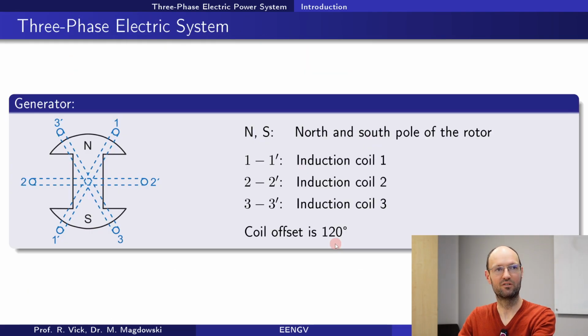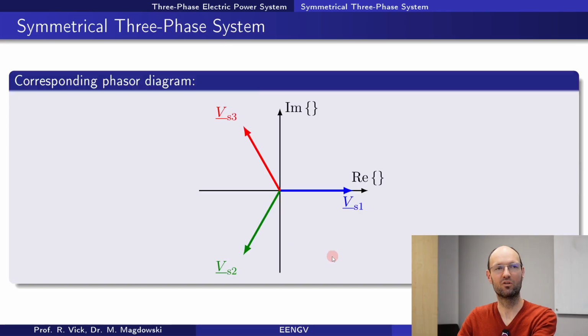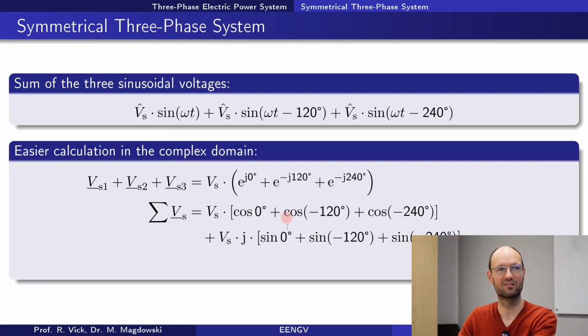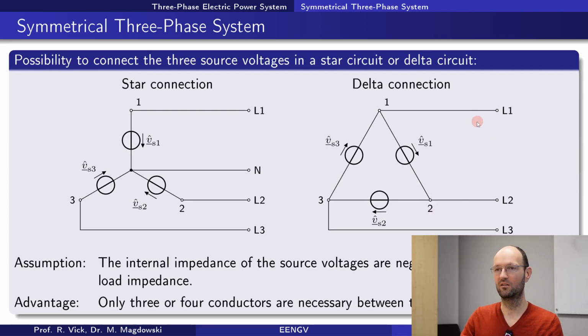And the advantage of this interlinking, this connection of these voltages, in German we say Verkettung. I've not really found a meaningful English translation for this, but all the mathematical properties that we just discussed, that the sum here is 0, this helps us in the end so that we can transmit 3 times the power of the single-phase system by just adding a third wire. That's a huge advantage for power transmission, for energy transmission.